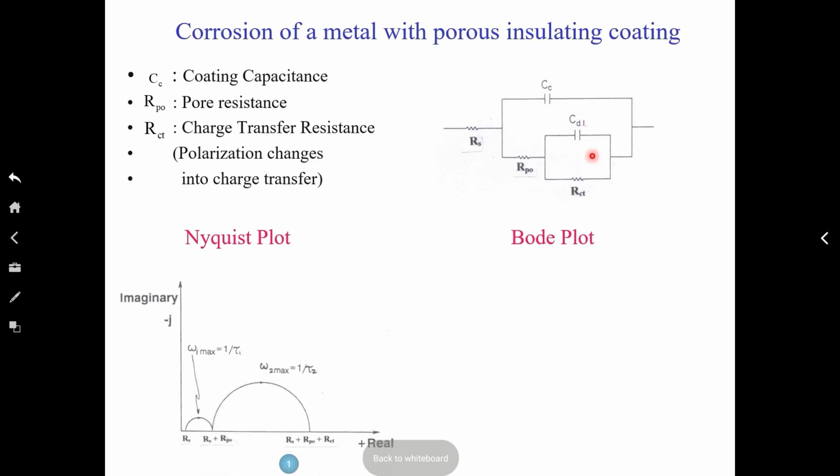So if you do the circuit analysis, do your math, and make the impedance plane plot, imaginary impedance versus real impedance, you can see how many R do you need? 3. You will get 1 from the first intercept.